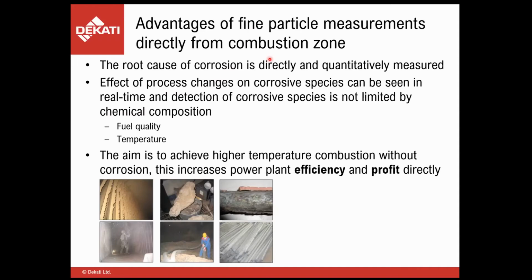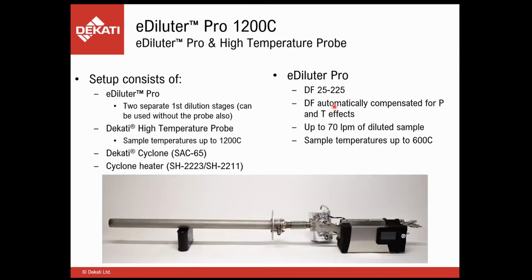So we have a question, how long can the high temperature probe stay in the flue gas stream? And is the probe cooled to prevent damages of the high temperature probe itself? Yes, so the probe itself is cooled. It's regulated to roughly from 200 to 400 degrees Celsius. So we drop the temperature in a controlled fashion by diluting the sample right here at the tip of the probe.